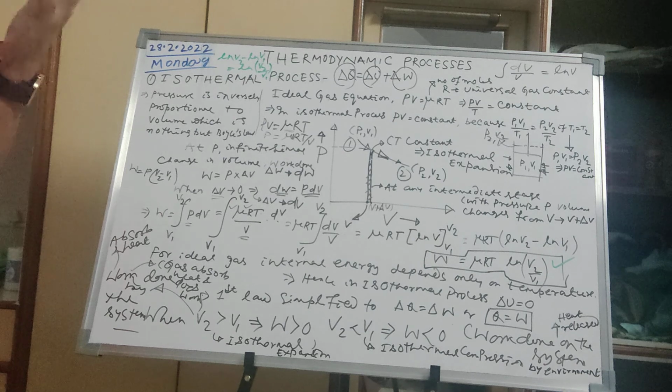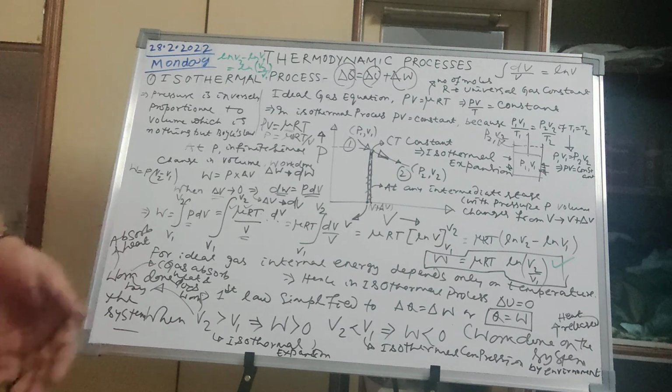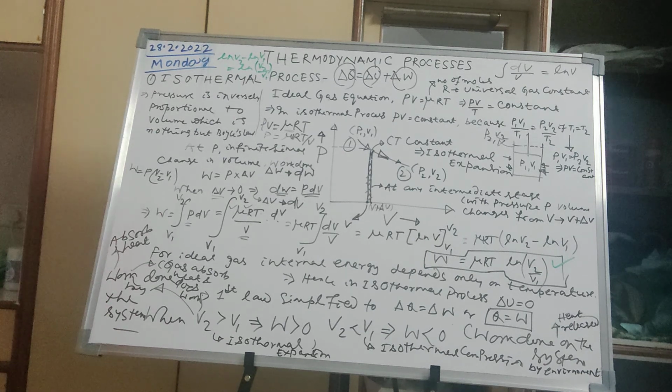That means whatever heat I have, like say petrol or diesel, it has some calorific value. Ideally I want the efficiency to be 100%, which is not possible because some heat will go to the atmosphere, because the exhaust gas is going to the atmosphere. So there will be some amount of energy remaining with that. So I cannot use 100% of the energy. That's why the efficiency comes into picture. So our intention is always to increase the efficiency as much as possible.